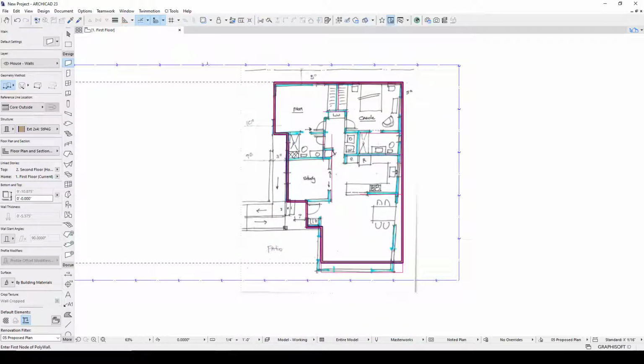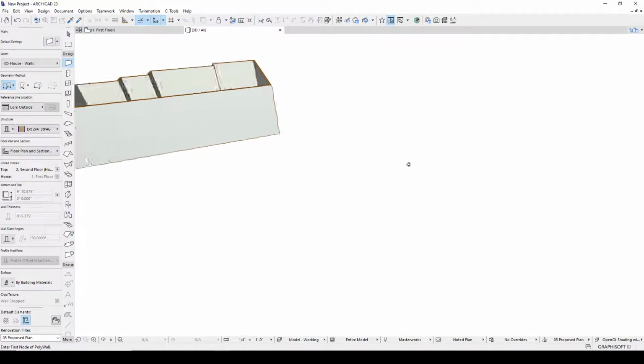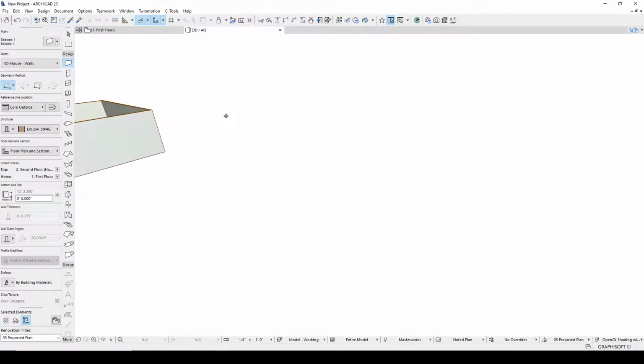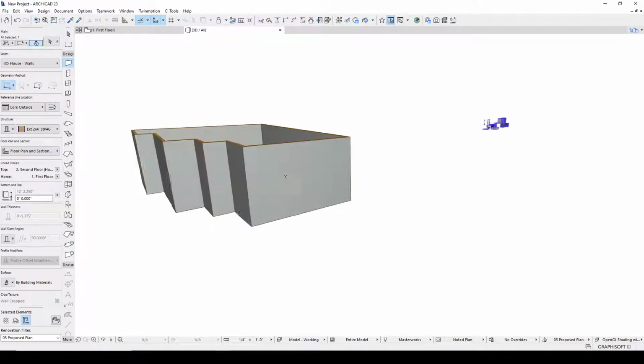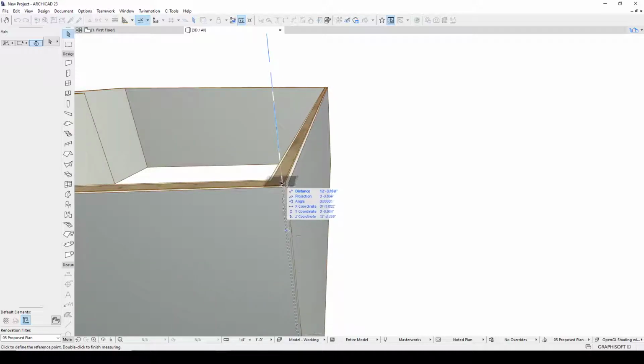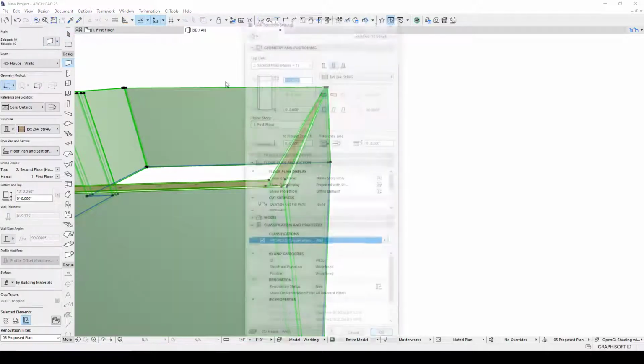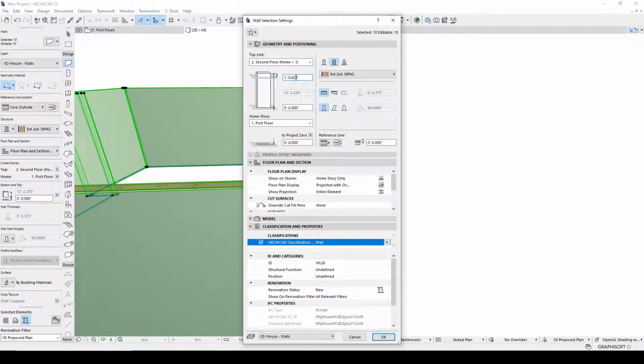So we can hit F3, double click the mouse wheel, and that's going to give us our 3D walls. And we can measure to make sure wall height's correct. It is not. And that's because when I do wall Control A, it should be a minus sign here.